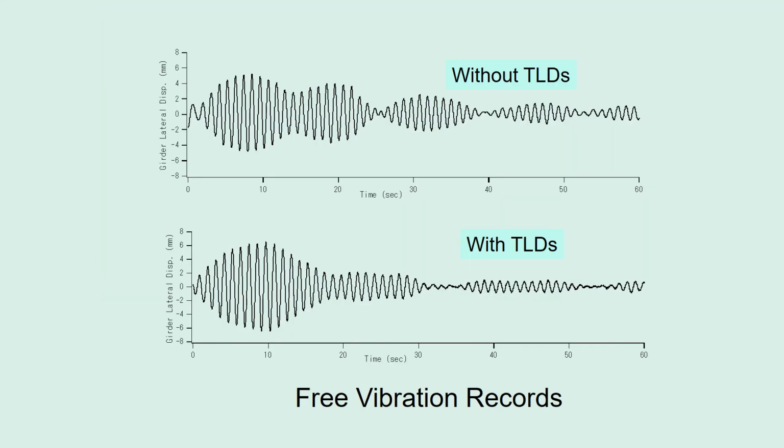I have to validate the effectiveness of TLDs. We let the girder vibrate and got free vibration records before and after installation of TLDs. The vibration with TLDs decreases more quickly than that without TLDs. It shows TLD is very effective.